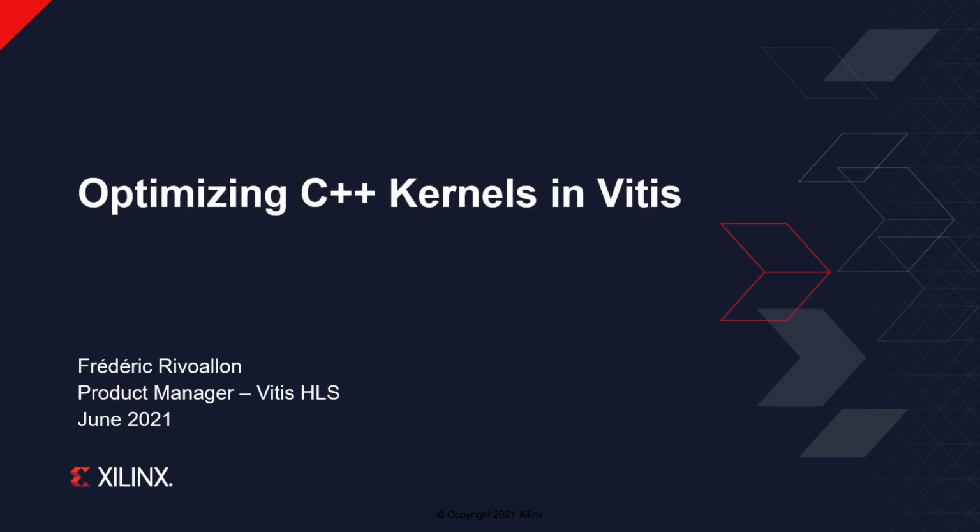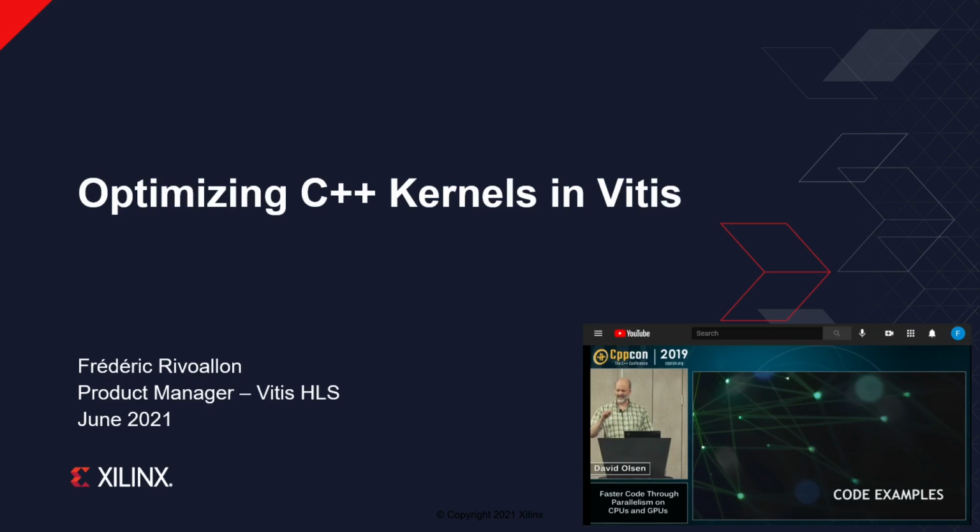So, hi and welcome to this Vitis webinar. We will focus on the creation and optimization of C++ kernels in the context of the Vitis flow. C++ kernels are the most natural way to implement an algorithm for Vitis, and it does not require the knowledge of a hardware description language such as VHDL or Verilog.